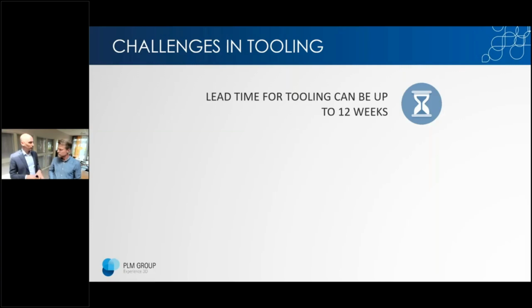Depending on which industry you're in, if you're working with injection molding, tools can take 6, 8, 12 weeks to get in-house before you can start actually producing parts. Both production and shipping of the tool. Many companies today use China for manufacturing of tools, but it's still several weeks, no matter what type of tool you're ordering.